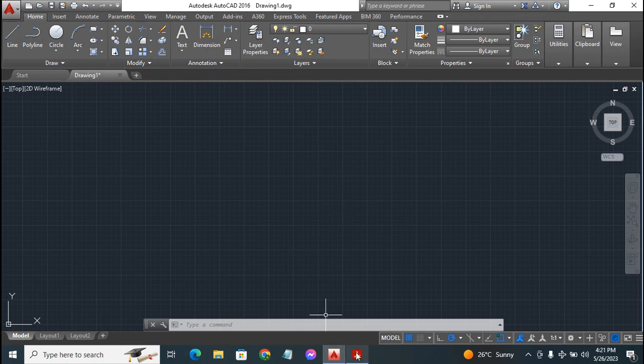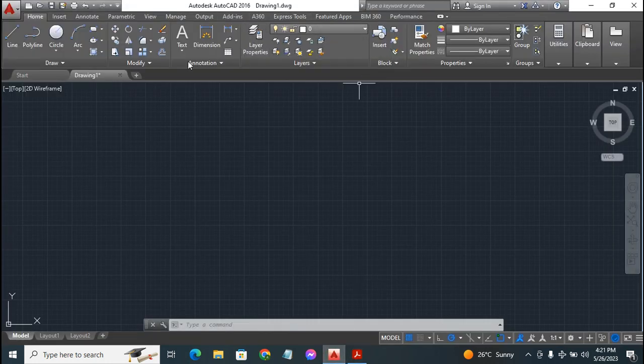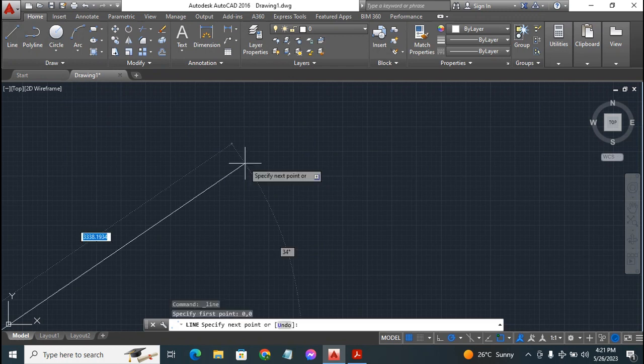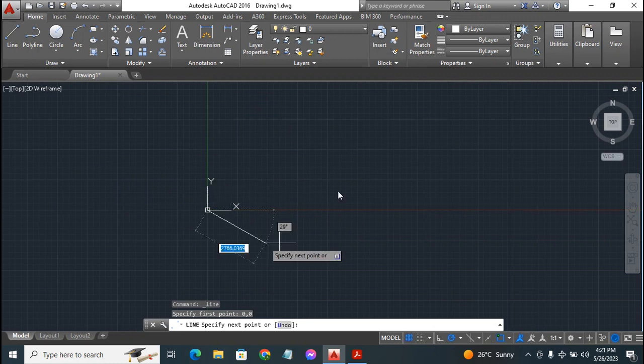Now next up, we'll go back to our PDF document. I want us to start off from this circle, where my cursor is right now. I hope you can see my cursor. So we'll get the dimensions of these circles. The dimensions are radius 24 and radius 60. Alright, we'll go back to CAD. You click line. I'm going to start off from the origin, so you type in 0,0 and press enter on the keyboard. That's our origin.